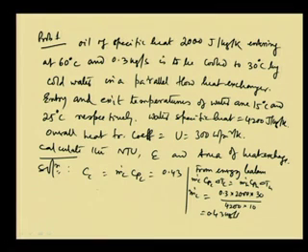So, once we know m dot C, we can calculate Cc. This is equal to 0.43 into 4200, which is 1806 joule per Kelvin, and Ch, the heat capacity of the hot fluid, is equal to m dot H Cph, which is 600 joule per Kelvin.